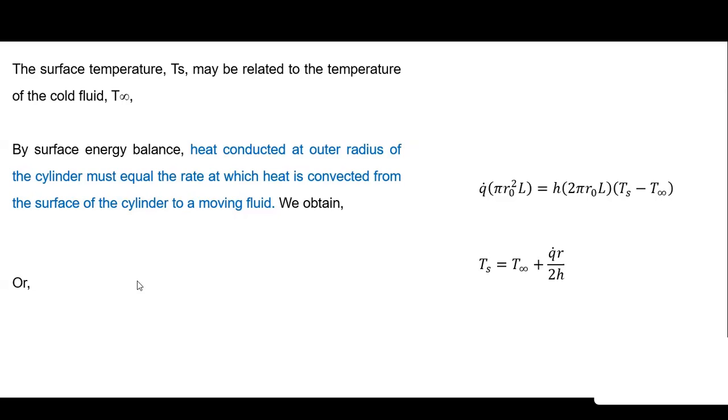Now I would like to add one word of caution for this. Whatever equations we have derived for the plane wall and for the cylinder system, except the temperature gradient equation, temperature distribution equation, and the general form of the equations, all other equations are dependent on the respective boundary condition. So don't use them for all types of situations. This particular equation, whatever I have written, is applicable only when there is thermal symmetry and a convective boundary condition. So this is a word of caution. So you cannot use this equation anywhere.